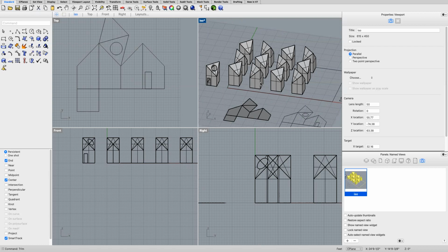One of the things for any kind of skylights that you're adding to your project, just kind of general rule of thumb, you want to face them to the north, because like this window is in the north, you don't get a lot of direct sunlight into it, even though you get a lot of light in it. So you want light, you don't want direct light.